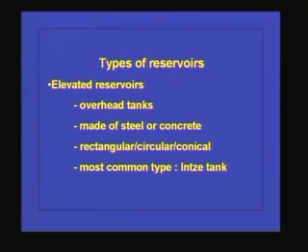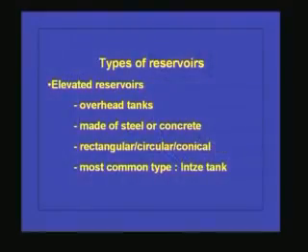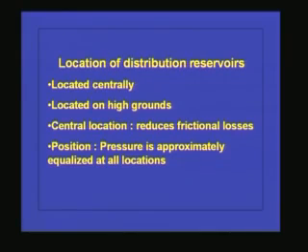Now these elevated reservoirs can also come in different shapes and sizes: a rectangular shape can be used, a circular shape can be used, and a conical shape can be used, and so on and so forth. The most common type of elevated reservoir is an INZE tank. Now the location of these distribution reservoirs depends upon the topography of the area and how uniformly you want to maintain your pressures.